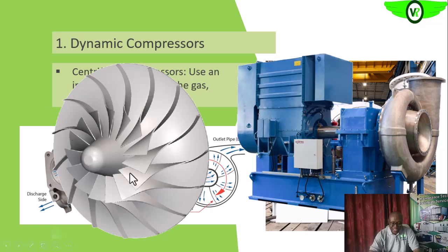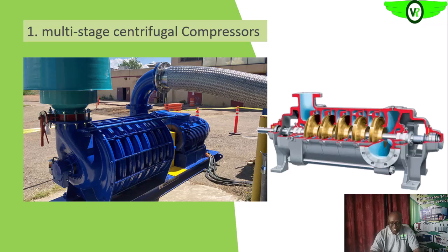And this is the main active component, which is the impeller. You can see the vanes on the impeller. These are the parts of the impeller that help to accelerate or add velocity to the gas molecules. So, as you see, all of them have their function. If any one is missing, that can reduce the efficiency of your compressor. So we should put this at the back of our mind, the function of each and every component, especially the active ones.